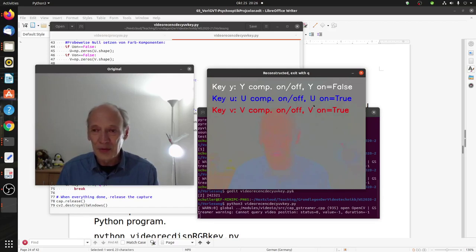The only way the pixels differ is on the color, and the color can only be recognized by the cones, and we don't have that many. And that's why we can actually reconstruct the U and V components with much fewer pixels than Y without the eye noticing, because the eye doesn't have that much sharpness resolution for those color components.